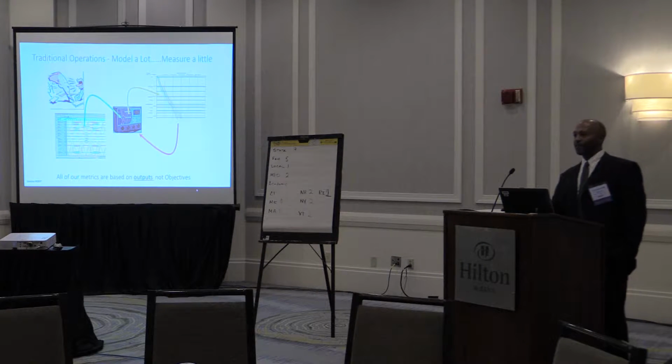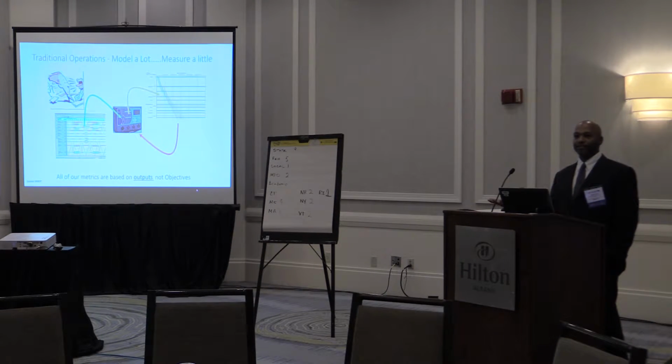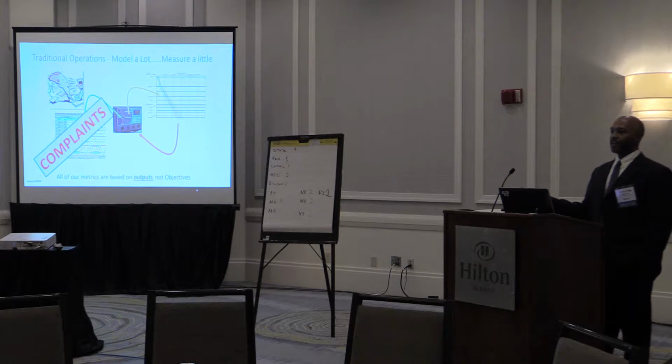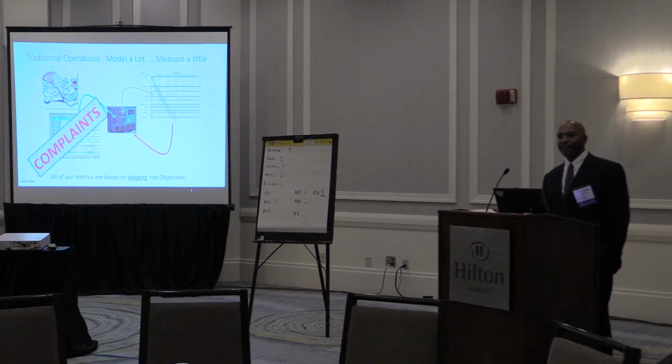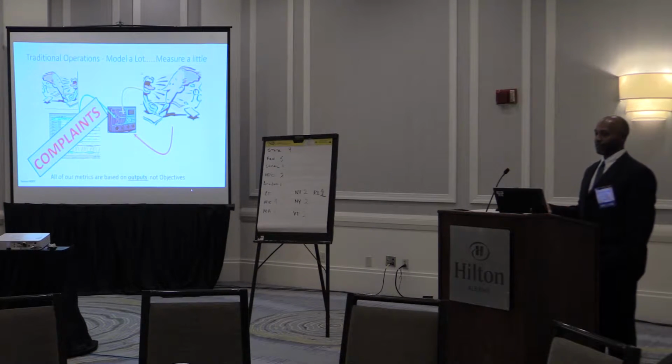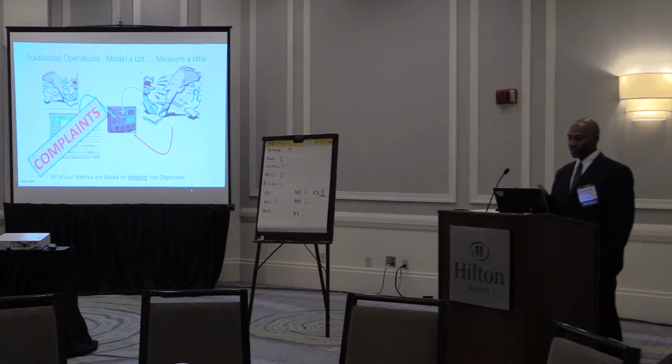In between the time that we do these retimings, we tend to get complaints as our performance measure. A complaint comes in, and that tends to bypass the modeling because now we have a problem. Maybe it's a pedestrian time that's too short, maybe it's a bicycle that's not being detected, maybe it's a side street that doesn't have enough time, or maybe it's vehicles not able to flow down the street without stopping at multiple reds. So we go out and make some changes. Because that model was designed on representative data for the intersection, when we start to get complaints, we're getting very specific items, and we make these tweaks, and they may not always work. So what happens generally is we get more complaints.